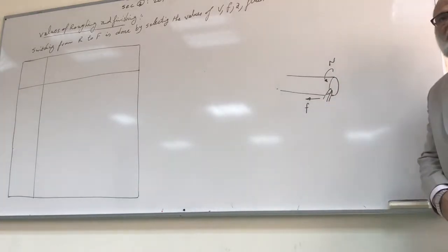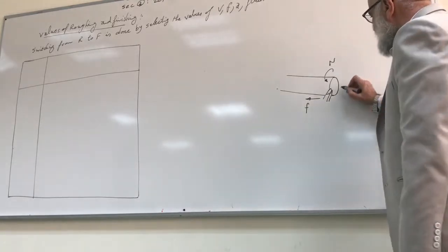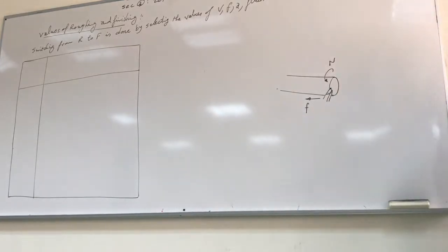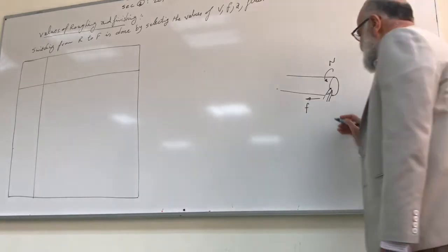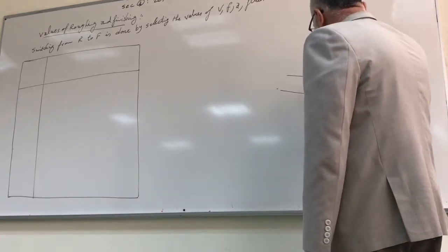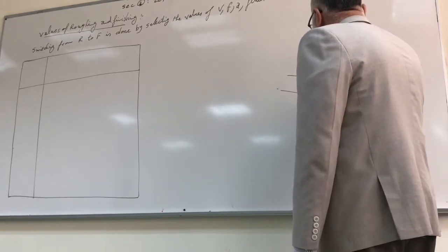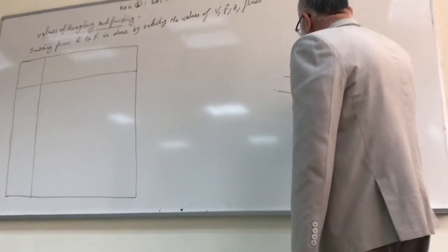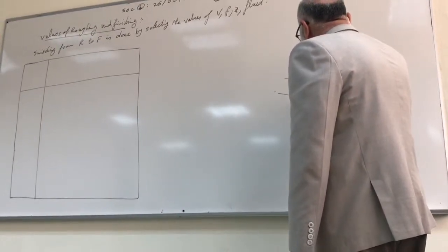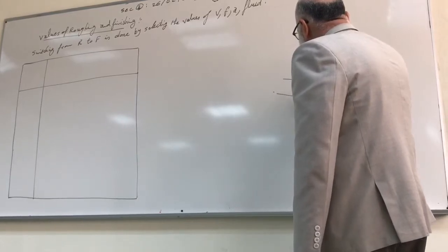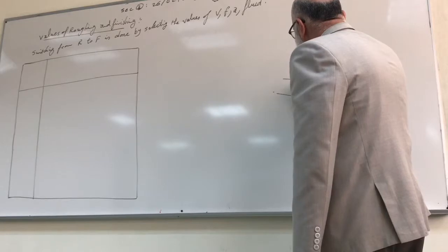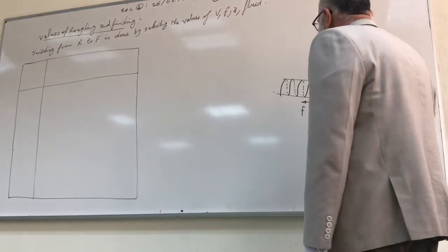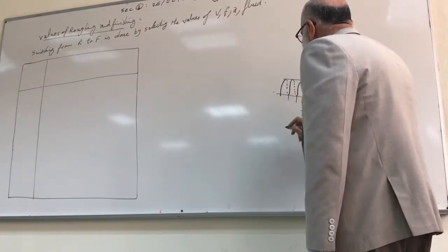What will be the shape of the locus done by the two motions? Spiral. I expect a spiral when the tool moves like this and that one rotates, then it will cut this way. On the other side, dotted, then every time the tool shifts axially a certain distance, this distance equals the feed F.